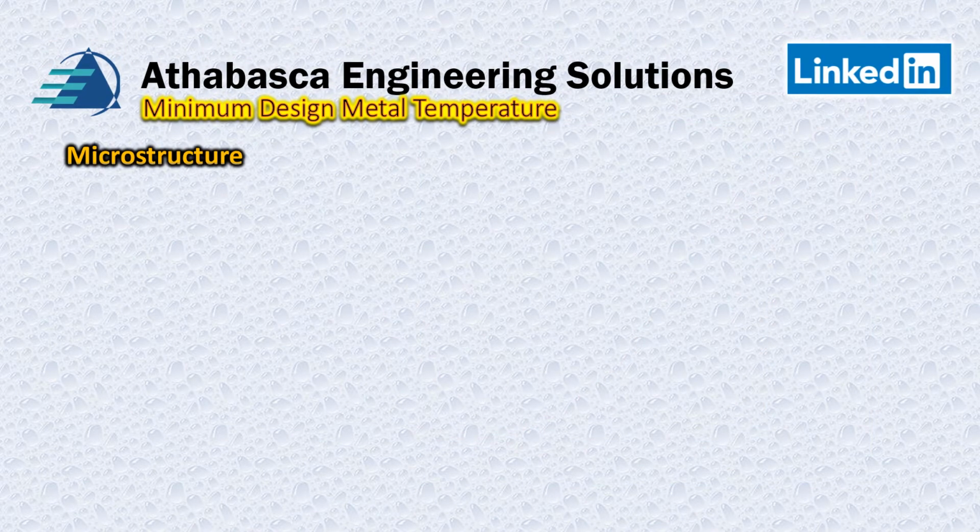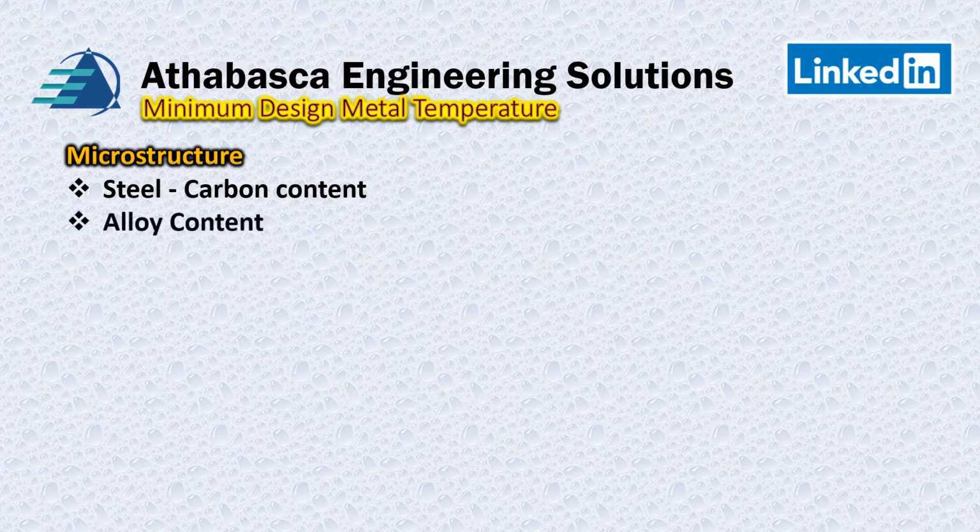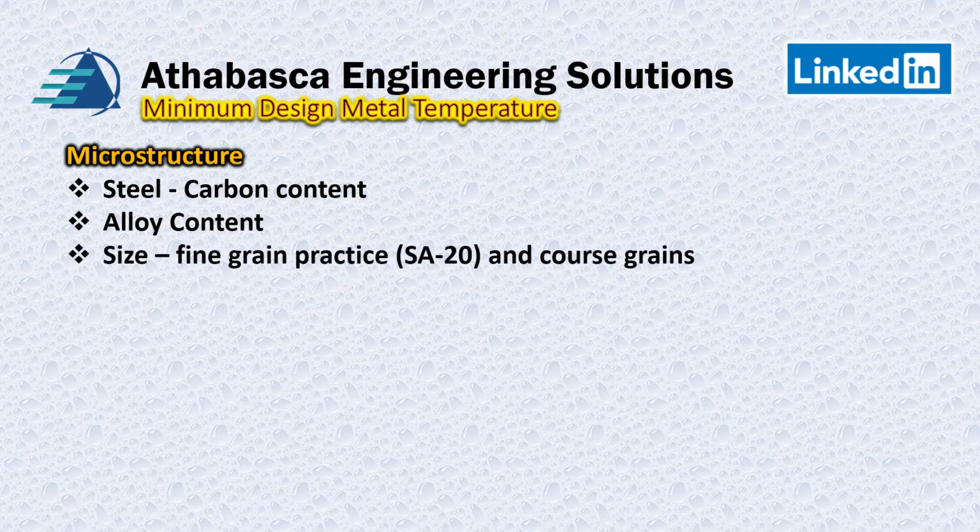The microstructure is so important when it comes to how tough a steel is. The microstructure is affected by things like the carbon content, the alloy content, and the grain size, and grain size plays a very important role. A fine grain practice is what you'll see with impact steels, where the grains are controlled with heat treating and the steel making practice, and even alloying will affect the grain practice.